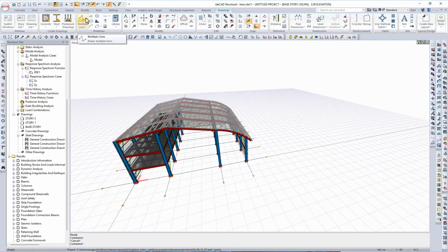The drawing module in ideCAD offers a full-featured 2D CAD environment, designed to support technical drafting with precision and flexibility. Inside this module, you'll find all the essential tools for two-dimensional drawing, such as line, path, circle, arc, and three-point arc. You can also add revision clouds and access editing commands such as move, rotate, mirror, or even rotate building. There are tools for scaling, trimming, and extending, as well as options to create and explode blocks, offset, divide, join, and clone elements, allowing you to modify your drawings just like in a traditional CAD platform.